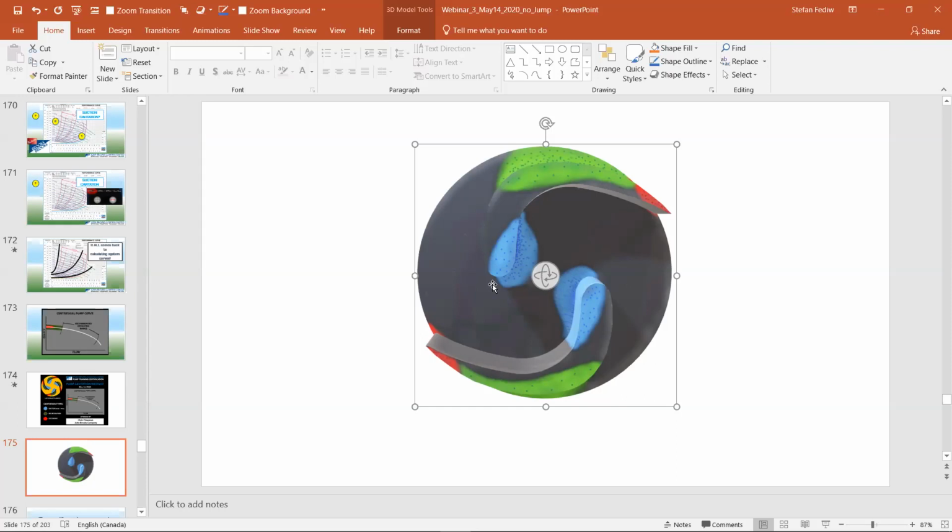So operationally it could be a number of things. If the pump was fine when it was started up, obviously you could end up in an accidentally closed valve situation. You could end up where the discharge piping has perhaps scaled over time, and maybe is forcing the pump to run a little bit left on its curve than it did originally. Running below that minimum continuous safe flow, you are starting to push the duty point towards the left-hand side of that pump curve.